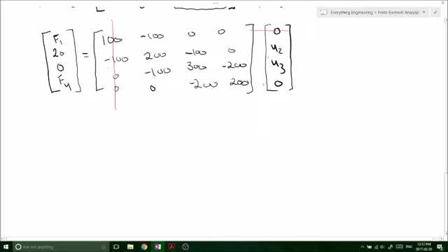Similarly, we have the fourth component of our vector being 0 as well. So now we can cross out the entire fourth column of our stiffness matrix, because it's all going to be 0 anyway. And because we want a square matrix, we can cross out the entire first row and also the entire fourth row, and this will make it square.